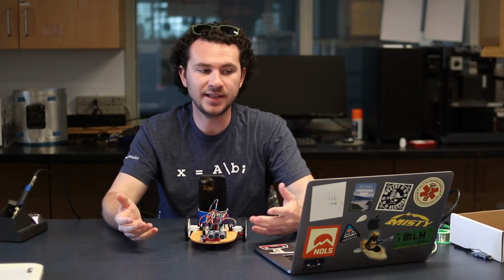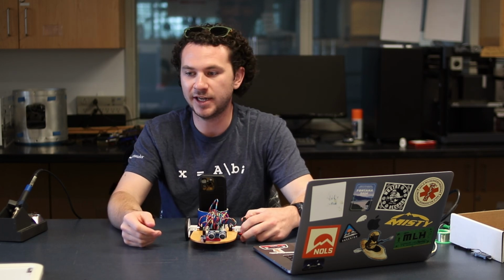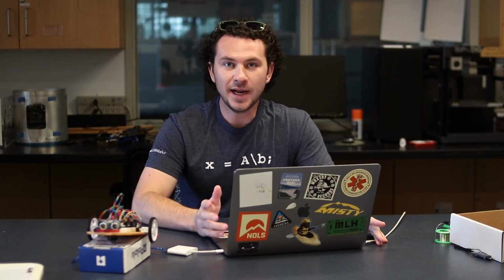By connecting the SDA and SCL wires in that fashion, we've just created that wire diagram that we showed for the I2C portion of this lesson. All right, now we have the IMU installed and we need to write some code to talk to it.